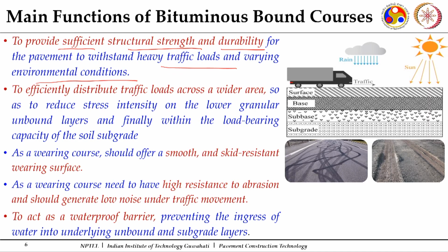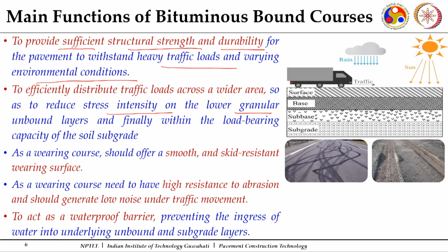Another aspect, they need to be strong enough so that they are able to distribute the load over a wider area, specifically so that the stress intensity on the lower granular and unbound layers gets reduced and remains within their load bearing capacity, ultimately when it comes to the soil subgrade.